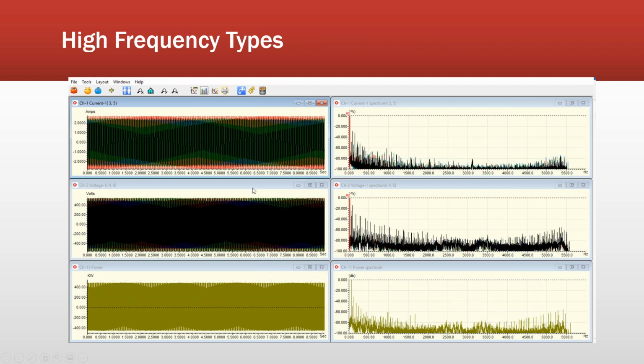Now, because I take 12,000 samples per second, that gives me a Nyquist of 6 kilohertz. 6 kilohertz covers everything in a turbine, including harmonics. Normally in a turbine, the firing frequency on the rotor drive, if it's a DFIG, is going to be somewhere around 2 kilohertz, so somewhere around 2,000 here. I'll see that, and then I'll see something around 4,000. I can use that to determine if I have an issue, and there's a set of peaks in between that will identify issues with the transformer. Down here, we'll take a look at this later.